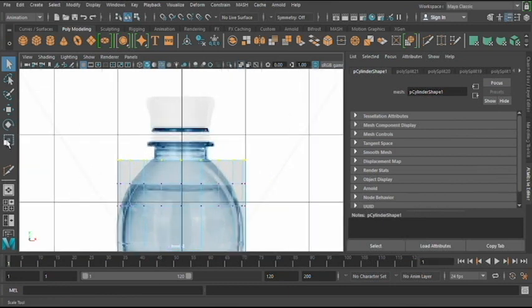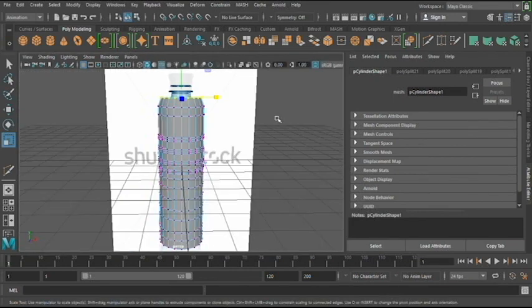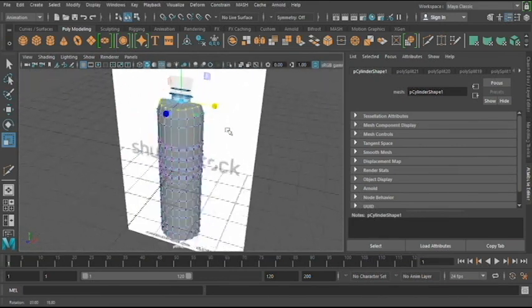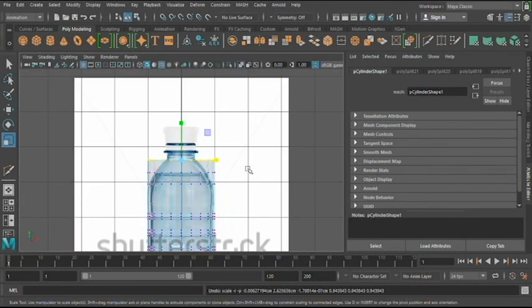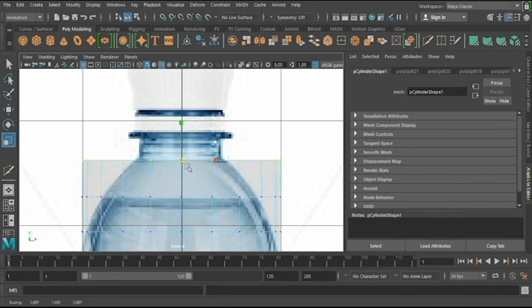Then I'm going to click the scale tool, and I'm going to actually scale this. Well, always make sure to do the center one, the center box over here. Click that when you're scaling. Do not scale with this, even though it might look like it fits over here. It will only be scaling that axis. It won't be scaling both axes. So let me just Control Z. Yeah. Okay. So I'm going to use the center one to scale in everything.